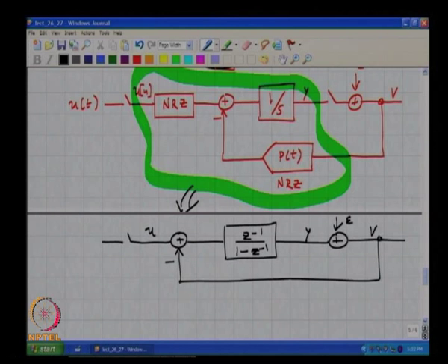You understand? But before we go there, we will also see what happens when u of t is not really a low frequency signal. The assumption so far has been that the input to the sigma delta loop is oversampled, which means that some sampling has taken place before, which means that before we sample we know that we are going to put an anti-alias filter which is going to cut off stuff at multiples of the sampling rate, right.